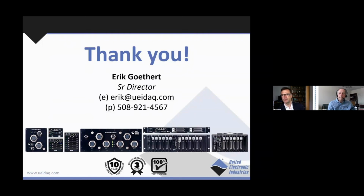This was quite early on in the presentation: if there are two buses, then how can one determine which bus has the valid data if the data received is different between the two buses? Well, in 1553, each RT is hooked to two different buses, bus A and bus B, for redundancy. So the bus controller will send a message on bus A, and if it does not receive a reply, it will send the same message on bus B. So the data should be the same. It's just a question of which bus it is coming over.